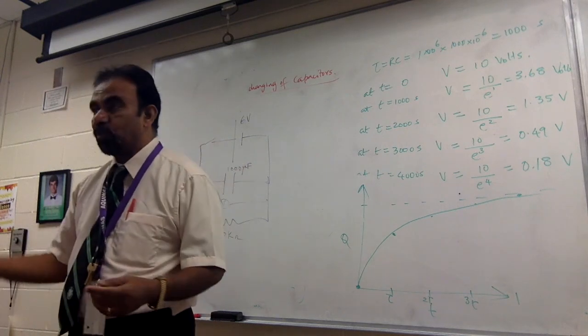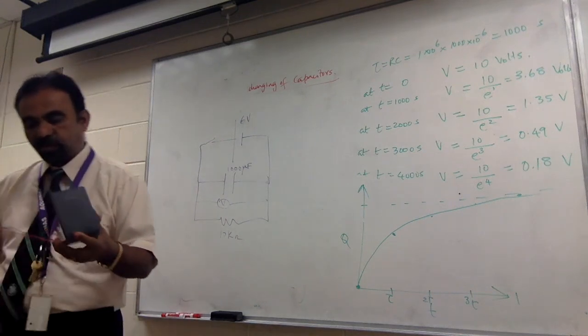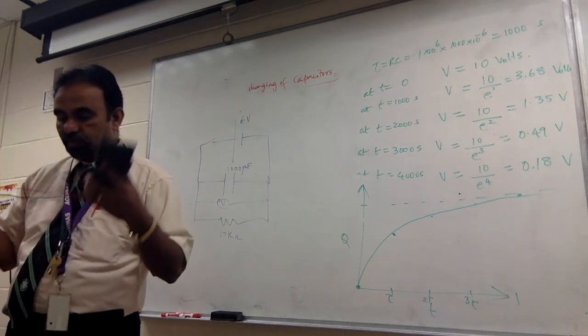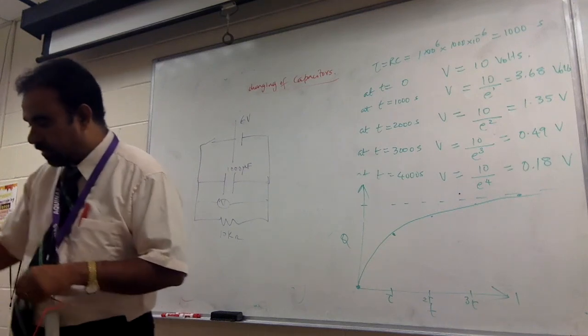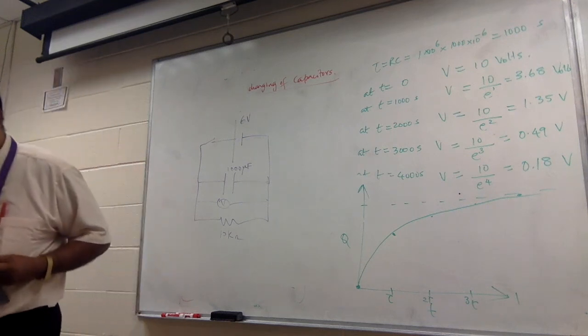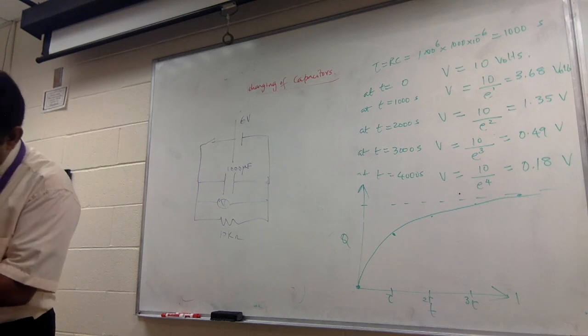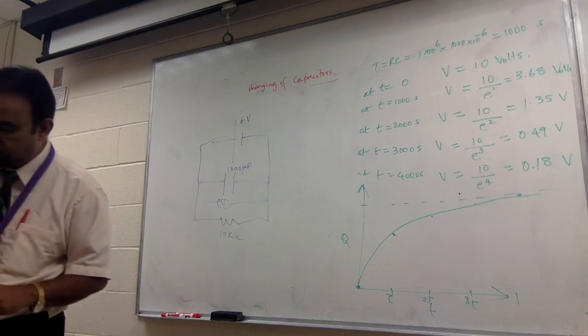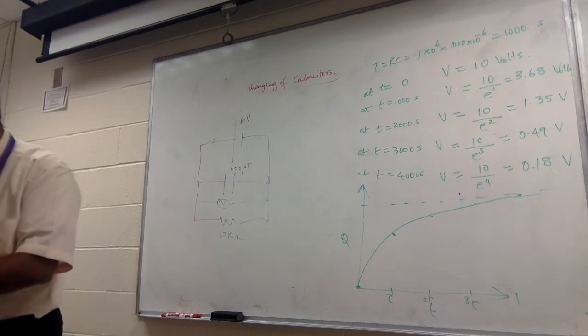And then I need to connect the voltmeter across the capacitor. So the positive of the voltmeter should go to the positive, and the negative of the voltmeter should go to the negative. Now, positive is right there. I'm going to plug this in somewhere. That should stay. Positive connected, and the negative.